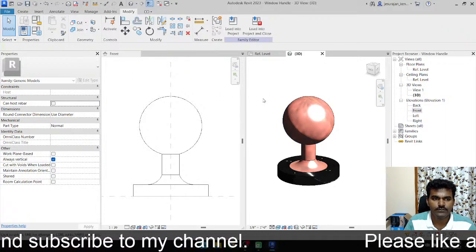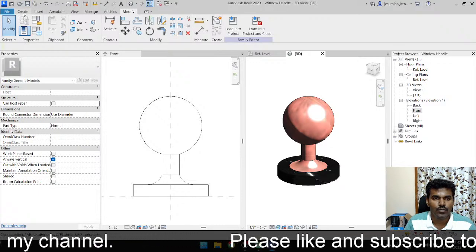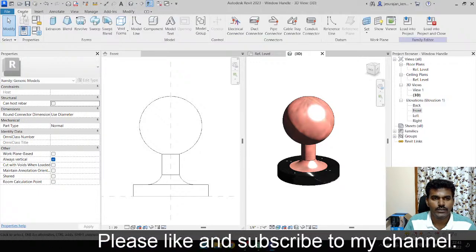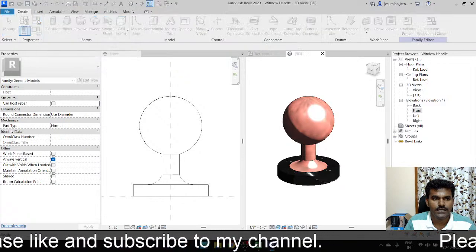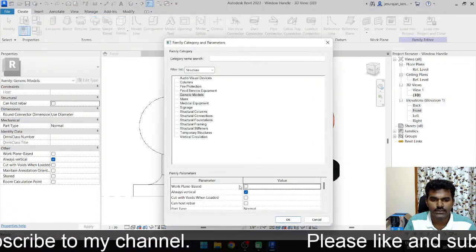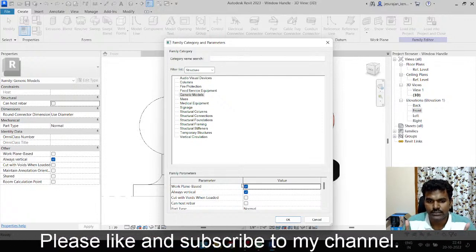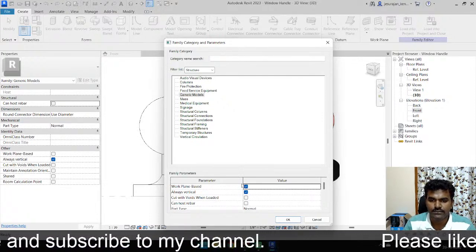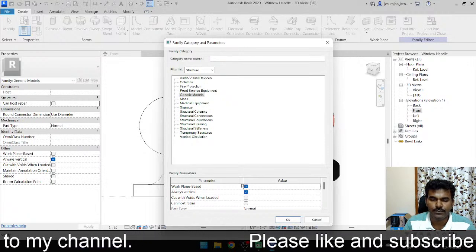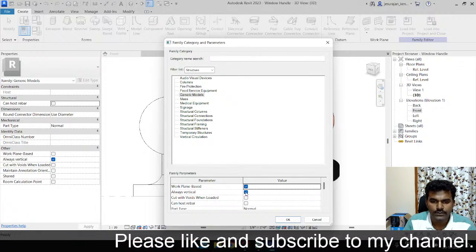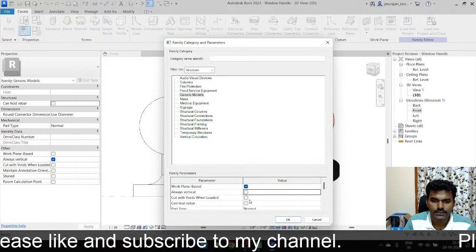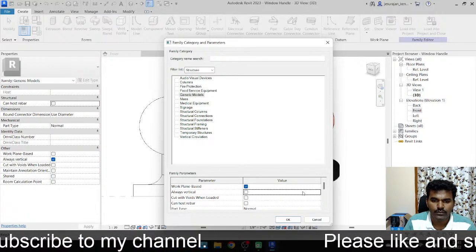Just save it. Okay, now go to create. Here select family and category. Keep this as work plane based, so then we can keep it as horizontal, vertical, so whichever plane we set, we can just keep our handle there. Always vertical, that's not required. And cut with the void when loaded.